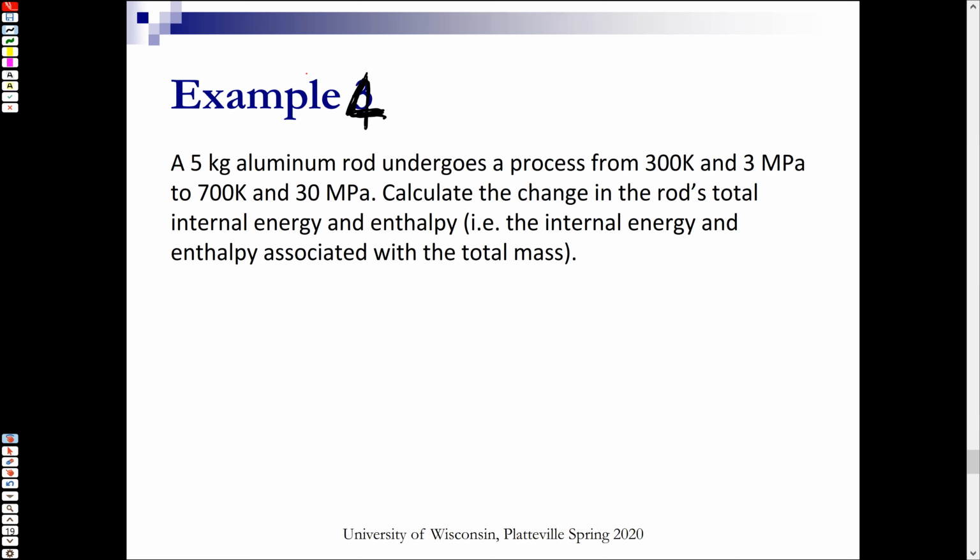Well, to solve this problem, I begin with the same procedure. I begin by going over the index of the tables, find the appropriate table, and then I read the properties from the table and try to solve it. The first table that I have to look at is the index to tables in SI units, page 921.